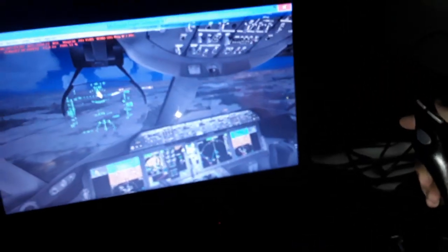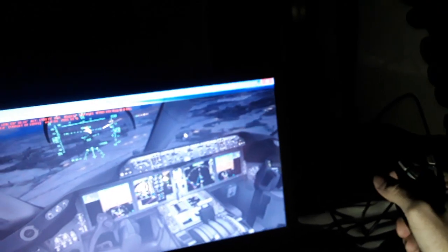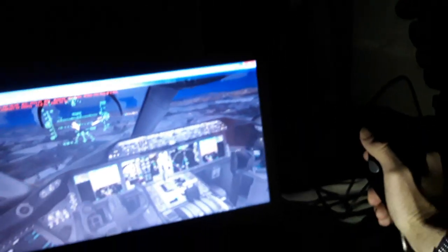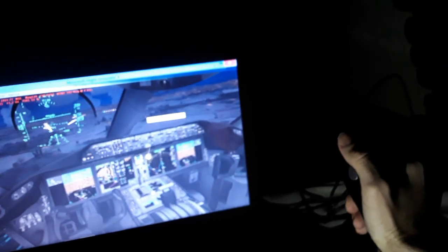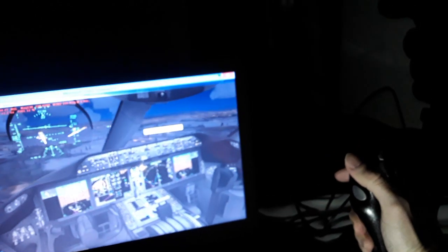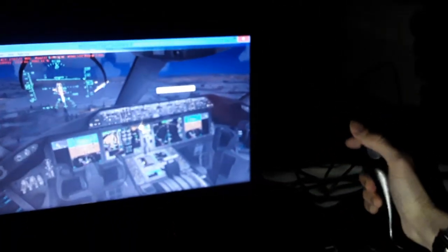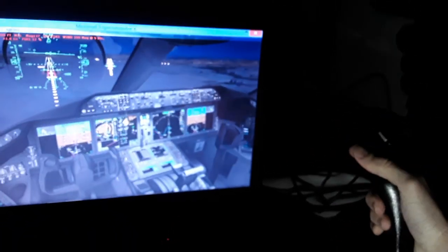So we have 1 more minute left. We need to use a bit more flaps, full flaps, increase the thrust. And approach, we need to align. We have some side wind, use all flight controls, ailerons, spoilers, rudder pedals. Need a lot of rudder pedal for alignment over here. So we have a few more seconds. Idle thrust now.